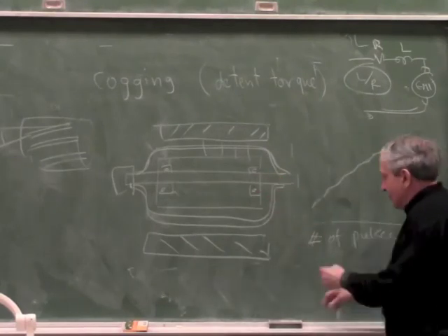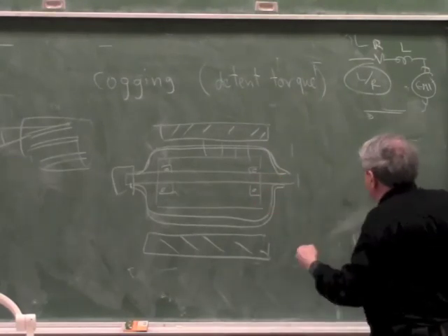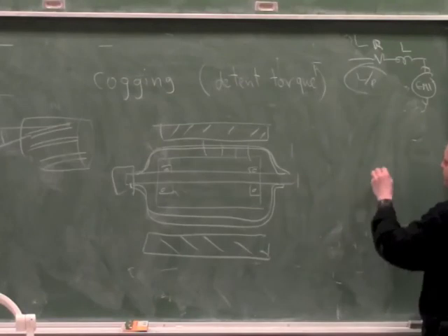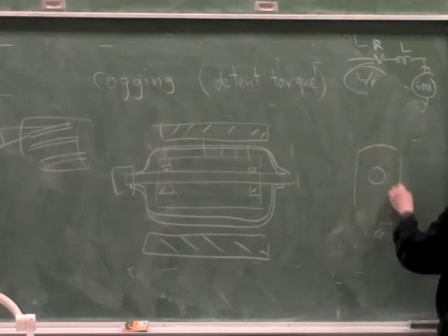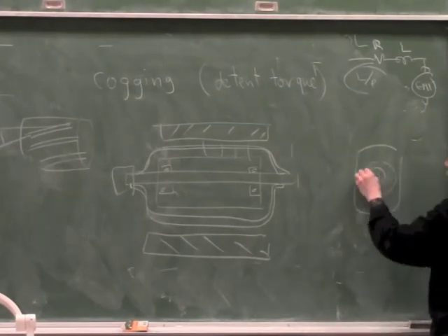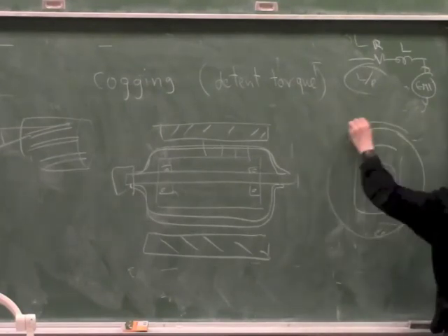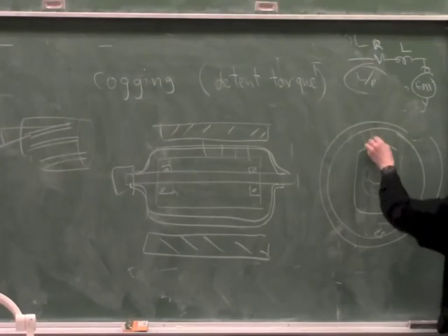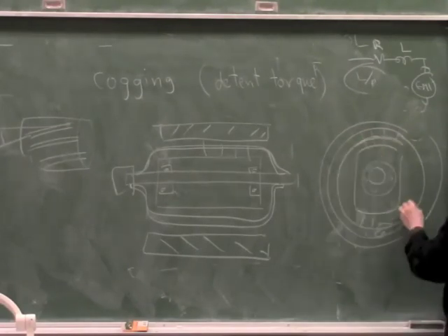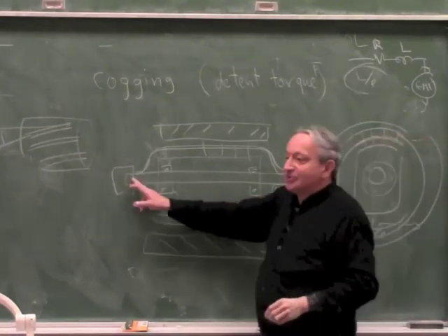So looking at the same motor in cross-section, you have a shaft, you have a magnet which is sitting on the shaft on a ball bearing, and then you have a ring of steel. Okay, the flux goes like this. The coil is sitting in between, but the coil can be supported in both ends now.